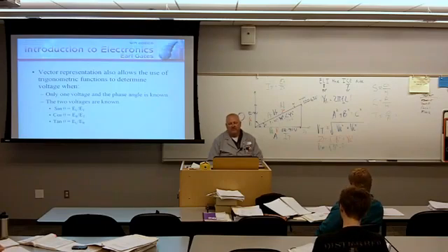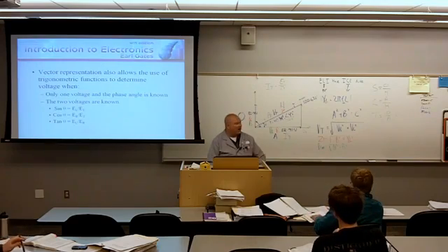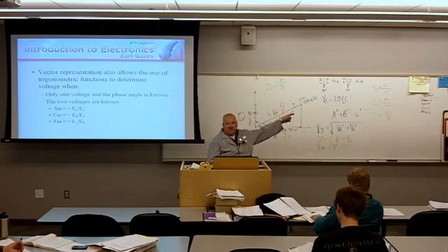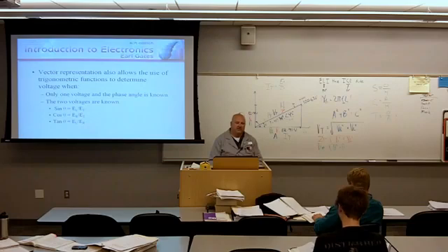Sine theta is equal to voltage of the inductor over voltage total. Cosine theta, ER over ET. Tangent theta, EL over ER. I remembered that over here by sine, opposite over hypotenuse. Cosine, adjacent over hypotenuse. Tangent, opposite over adjacent. If you can't remember that, remember some old horse came a-hopping through our alley.